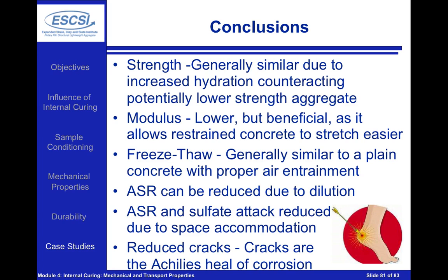Freeze-thaw resistance, we generally see a similar behavior to plain concretes, provided we have proper air entrainment. And remember, the self-desiccation is going to pull water out of the lightweight aggregate. So after a relatively short period of time in a low water to cement ratio concrete, we're going to have pulled the water out of the lightweight aggregate to cure our concrete, and we're not going to have a problem with the water remaining in the lightweight aggregate. So in general, internally cured concrete is going to behave very similar to plain concrete, provided both cases have proper air entrainment.